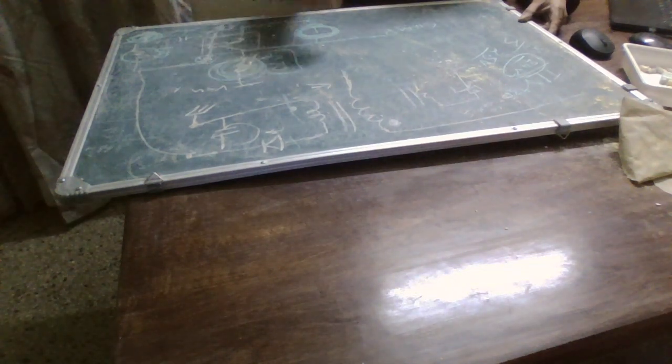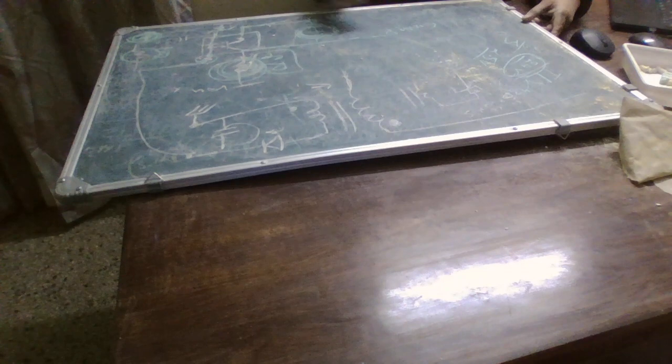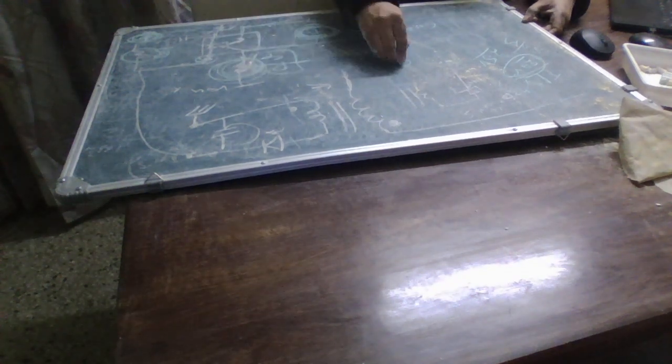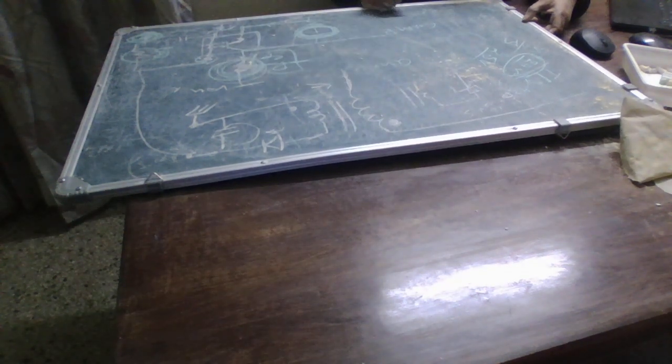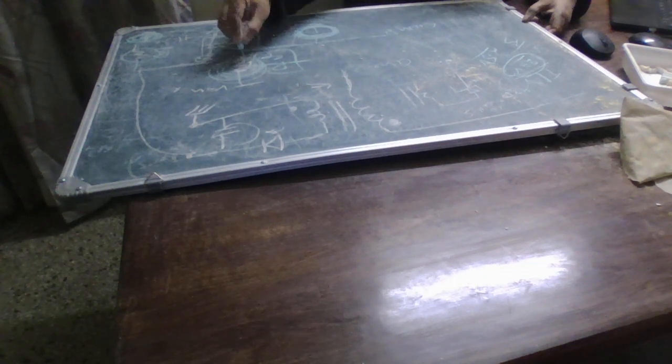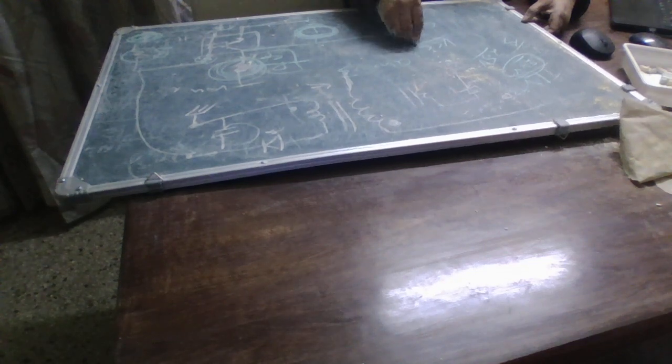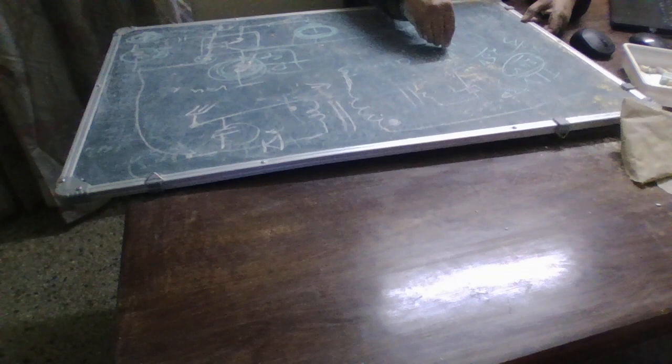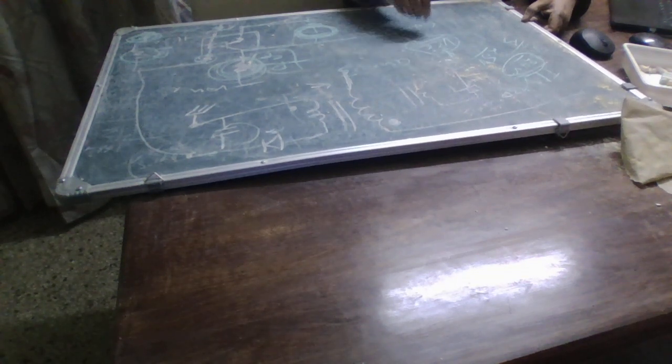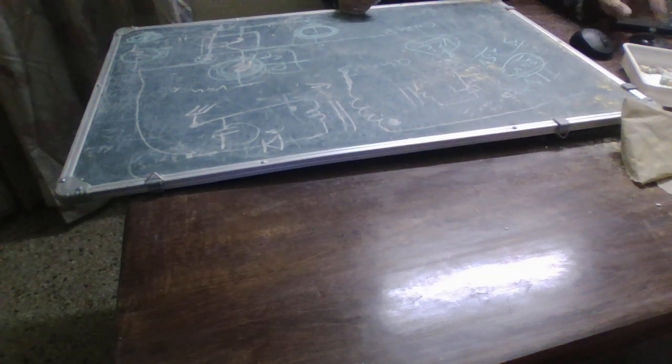This value we also need to select, and it depends on the auxiliary winding voltage. Or rather, if the flyback transformer does not have an auxiliary winding, I can use the VCC output pin voltage of this regulator of the IC which I have just mentioned.